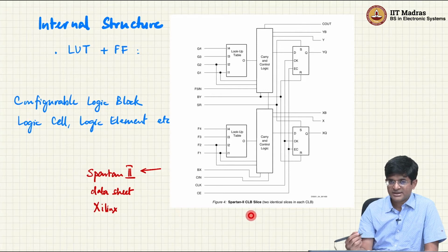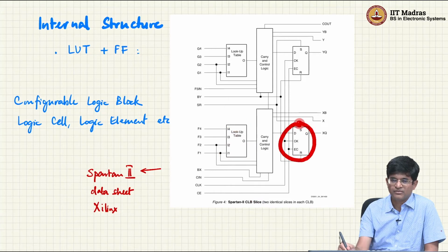This is a common thread that you will see as you go to more modern FPGAs. What the manufacturers have done is try to identify blocks that are more and more commonly used and then repeat them. They directly make hardware instances out of those blocks so that you don't need to waste time building them out of lookup tables and flip-flops.